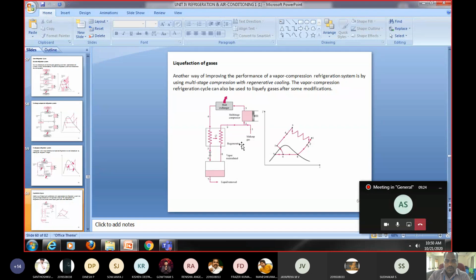The thing is we need to provide an additional regenerator. If you see in this flow diagram, the outlet from the heat exchanger is passed through the expansion valve. Regenerator: you know how the regenerator works. The regenerator takes the exit heat to reheat and regenerate the properties of the medium. So from 4 to 5 and 8 to 9 we attached a regenerator.